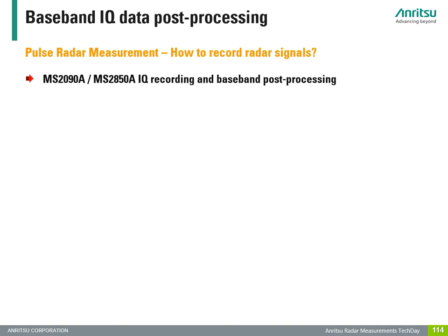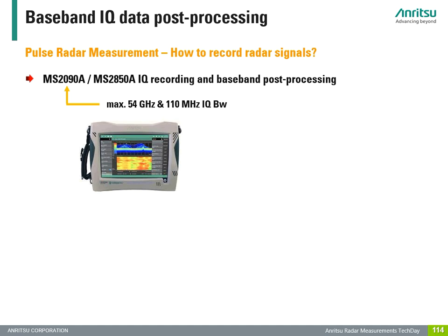MS2090A as well as MS2720XA and MX28XXA are coming into play here. All these instruments allow IQ baseband recording. The MS2090A platform goes up to a frequency of 54 GHz without any kind of external mixer, and a maximum IQ bandwidth of 110 MHz.